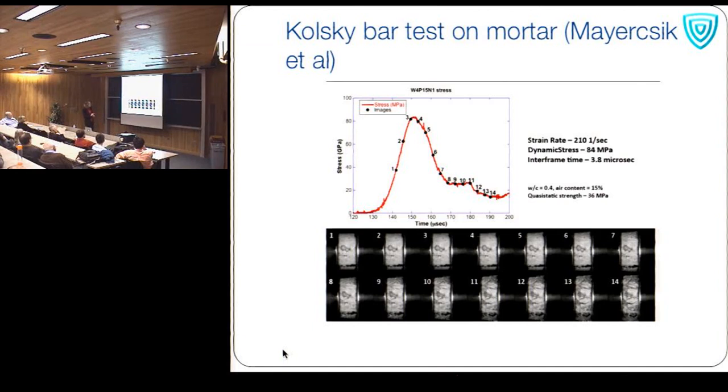And what I want to point to, it's always hard in a projector to see it. Maybe you can. But you can see this sort of axial splitting mode that's occurring, these sort of through cracks in the direction of the loading. I should have made it clear. The loading is a compressive load this way.